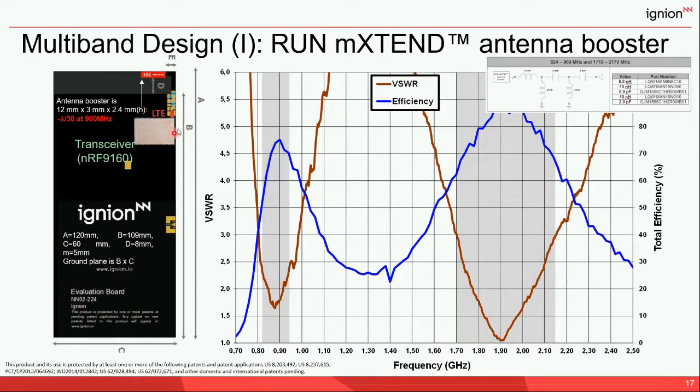Try to minimize the feeding line, the 50 ohm feeding line in red, to the matching network in order to avoid any interference or any losses. When the matching network is properly designed, in this case, it's a combination of 5 SMD components, size 0402. These are the typical components we recommend from Murata, for example, tight tolerance and high Q. These are typical components available from most component manufacturers. Sometimes you can use 0201 and 0603 SMD, but usually the most common is 0402 high Q tight tolerance.